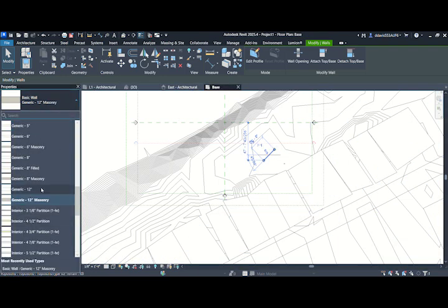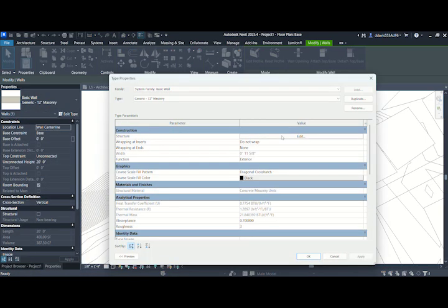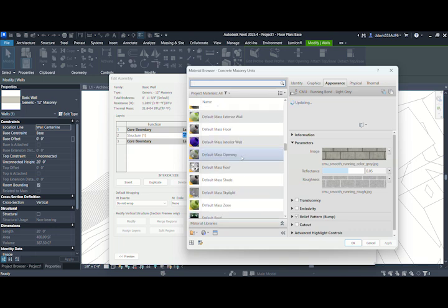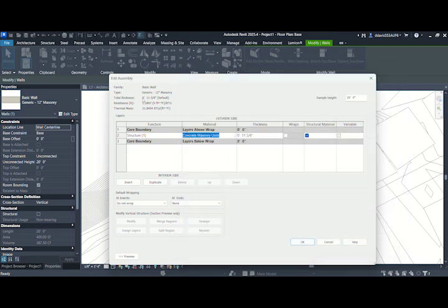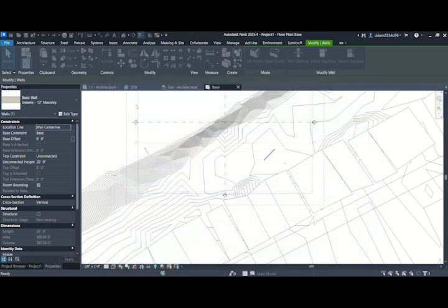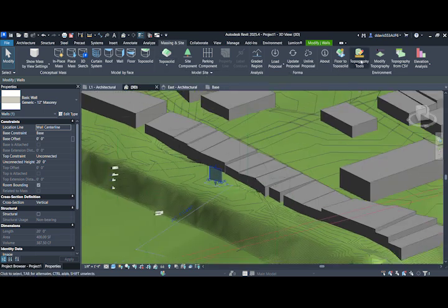I start by creating a level which my geometry can relate to within an elevation or section view. Then I'll go back to plan view to draw. I place a wall, specify its length, and set it to start at the base level and reach the level I created. Then I'm done. It's visible in all views, and when I go into that wall's properties, I can see some info related to the actual layers within the wall's construction and other info which can be edited.